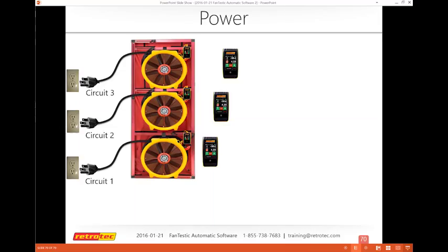Essentially, when the operator is moving around, for example, you're doing a combustion blind zone test, and you're walking around the house, opening and closing doors and so on, then you can do this by having your cell phone in your hand. You can be watching the pressure and so on, so you don't want to be dragging tubes all over the place. But if you're dealing with a static situation where the components, the gauges, etc., aren't moving, you might as well hardwire them together, even if that gauge is on the third floor or something. You want to hardwire them together because you're not moving around.